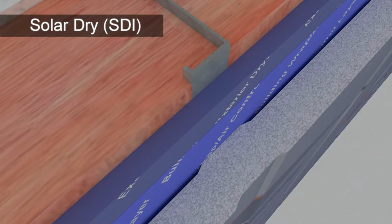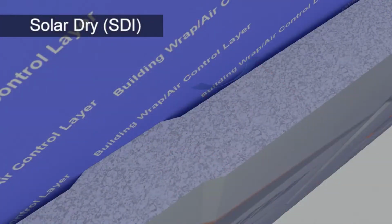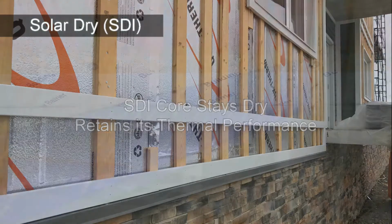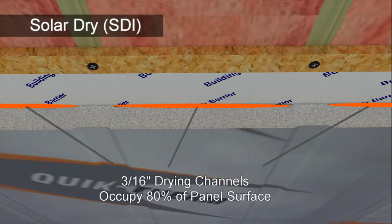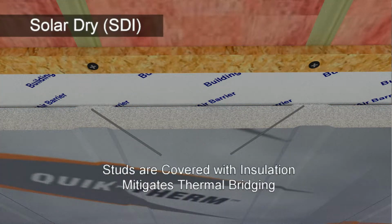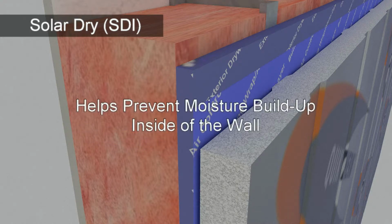Solar Dry's rigid Type 2 EPS core is covered with impermeable polymer facers that will not allow moisture ingress from either the interior or exterior. Thus, the insulation core stays dry and retains its effective thermal performance. On the sheathing side of the system are 3/16" drying channels that occupy approximately 80% of the panel surface. Moisture trapped in the wall cavity can exit to the exterior of the building wrap into the channels and subsequently dry or drain. This helps prevent the buildup of moisture and subsequent rot and mold formation.